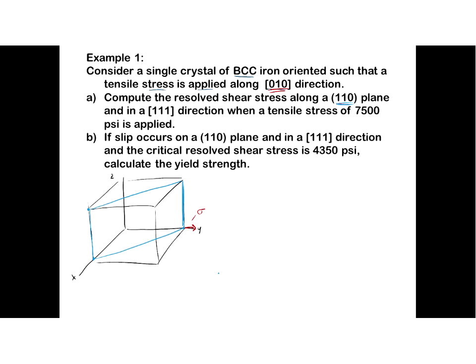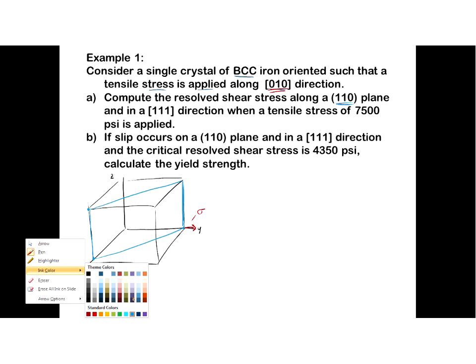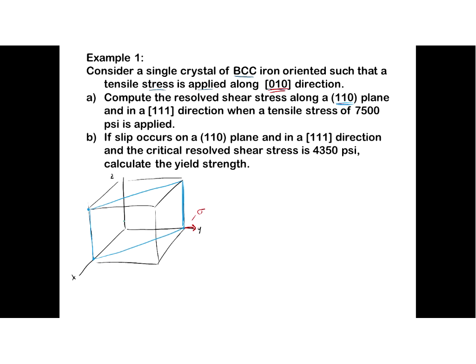Yeah, so instead of, hang on here, we're going to look at, we could talk about this as the 111 family of directions. I'm actually going to make this, let's say we're going from here up to this point. That would be in the 111 direction, right? Or it's in the 111 family. It's really in the negative 111 direction, right? Going from one corner all the way across to the other corner. Is that okay? We good there?